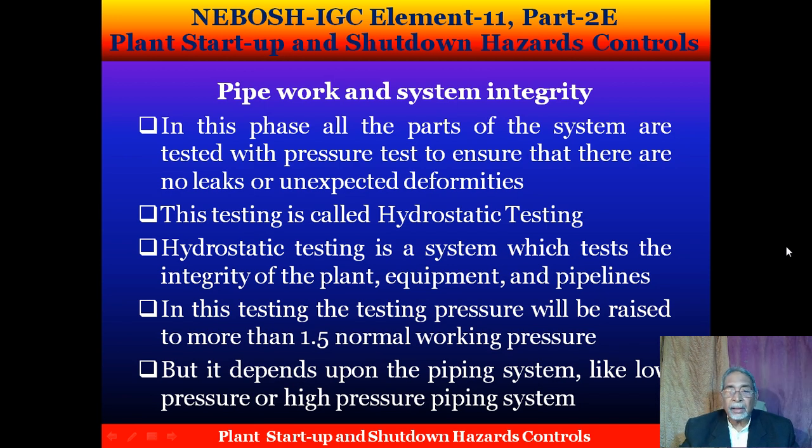In this testing, the testing pressure will be raised to more than 1.5 times the normal working pressure. But it depends upon the piping system, like low pressure or high pressure piping system.